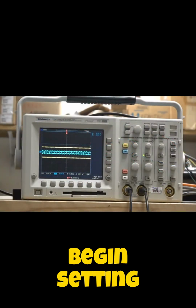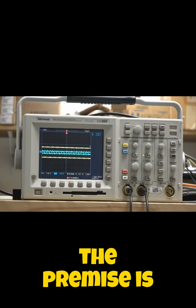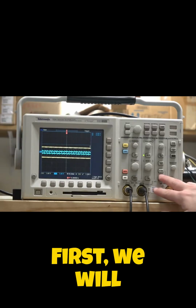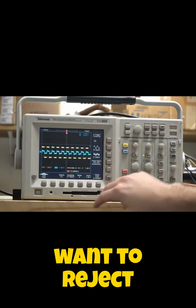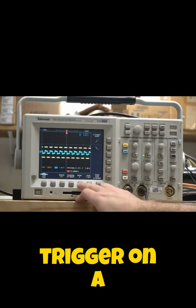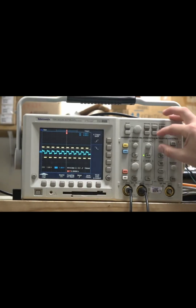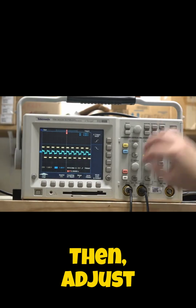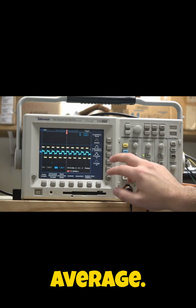Now, let's begin setting up the scope. Your scope may look different, but the premise is the same. First, we will check the trigger settings. We want to reject high frequency noise and trigger on a rising edge. Then, adjust the waveform acquisition to show the average.